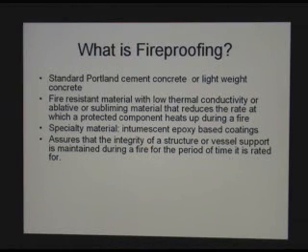Typically, the steel can heat up to about 1,000 degrees before it becomes unsafe. There are some specialty materials like intumescent epoxy, which is applied like a paint. If it gets into a fire, it puffs up into a thick layer, maybe 2 inches thick, and provides the protection.